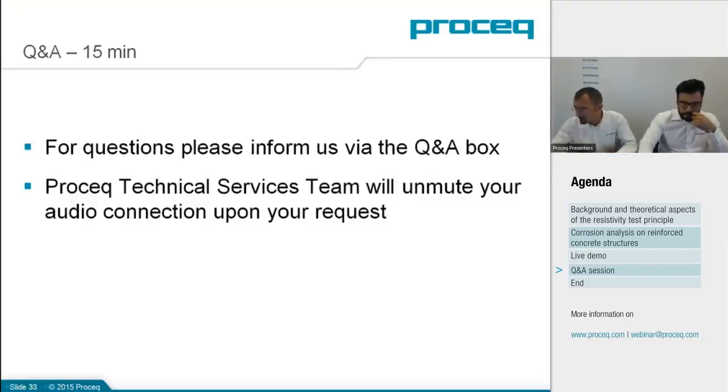Does the surface resistivity test use AC or DC, and what are the typical electrical parameters involved? We're working with a typically highly resistive material, so direct current won't be able to do that unless you use huge potential, which you don't want to do with your hand.